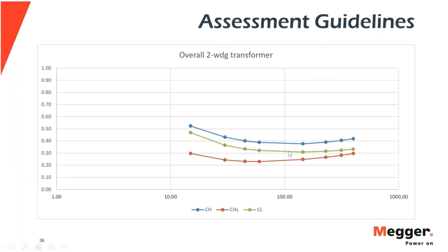There it is. It'll actually cause general shifting. Say we were testing right now at 40 degrees Celsius when these measurements were done. Well, if we correct it back to 20 degrees C, you'll see a general shift of all these curves towards lower frequencies. And of course, I'm looking at the 60 hertz frequency and the slope of the line